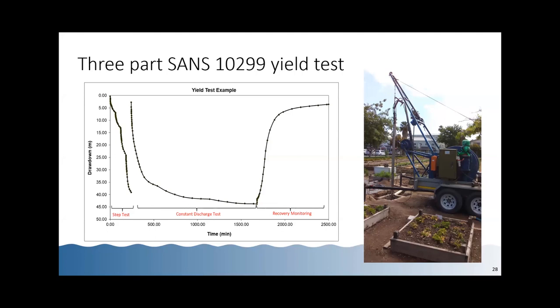Sometimes we have very high yielding boreholes that have yields of maybe 20 liters a second or even higher, and we do a constant discharge test and the water level drops very slowly during that test. We monitor it all accurately. The test lasts for 3 days. We switch the test pump off, and then the water level recovers maybe 30% and then just stops at 30% recovery for the next 3 days.